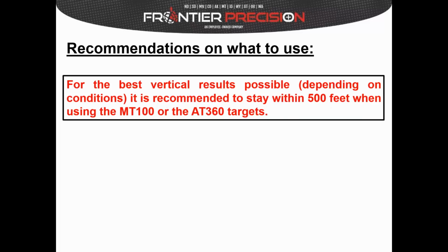I do want to throw a little note in here that for the best vertical results possible, again, it's going to depend on the conditions, but it's recommended to stay within 500 feet when using either one of these targets. If you're looking for vertical accuracy, keep your shots as short as you can.